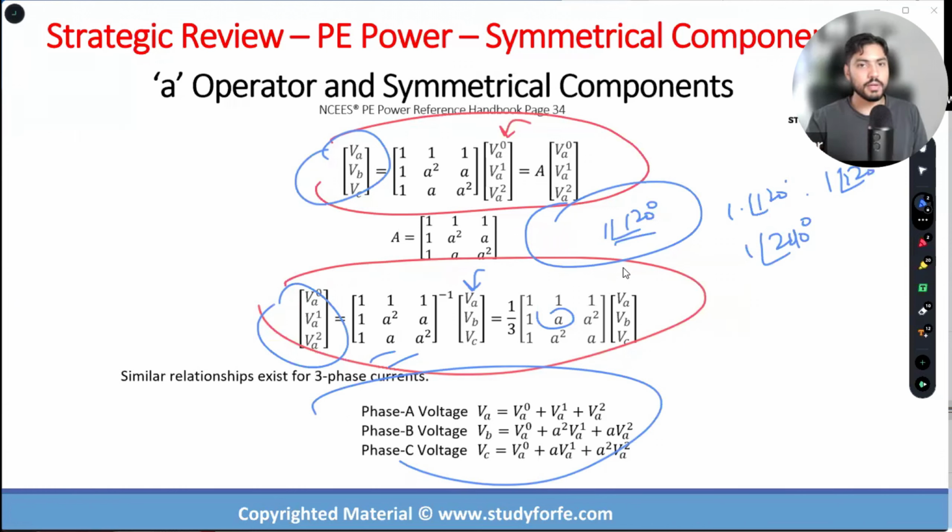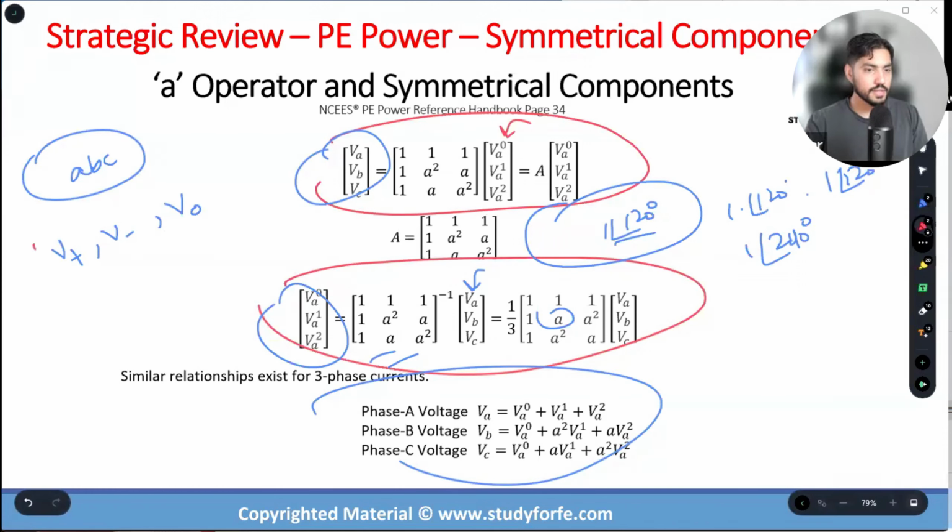And the final point I'm going to mention, as we discussed earlier, is that let's say we start out with a positive sequence network, which is ABC. If this positive sequence network is present, then I only expect to see, in terms of symmetrical components, this guy present, or subscript 1, okay? If it is balanced, then these two should not exist, okay?